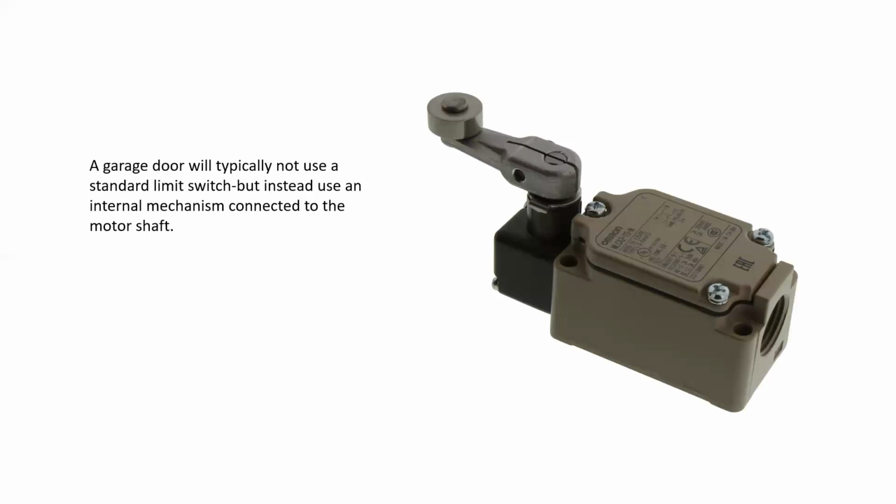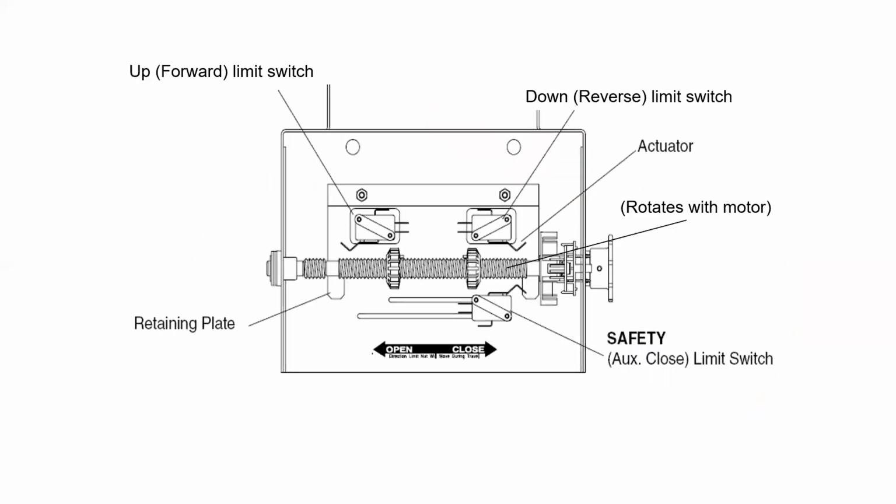Now, a typical garage door in a commercial or industrial setting will not have big chunky limit switches like this, as they would be really challenging to actually mount on the wall and come into contact with the doors. It's not really feasible. Instead, we use a rotating worm gear and a fixed collar. And the fixed collars you can see right here, they're actually threaded nuts. And the nut is held from turning.